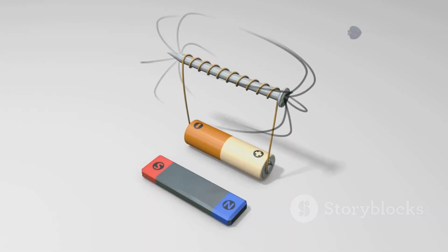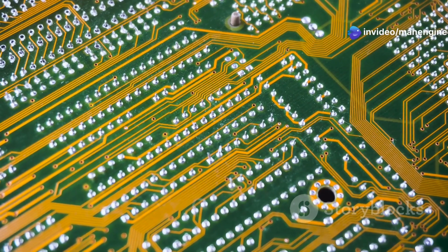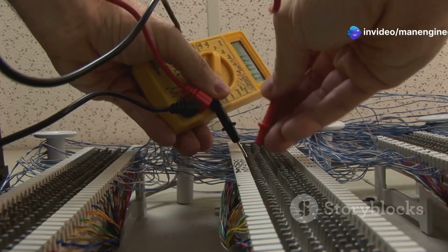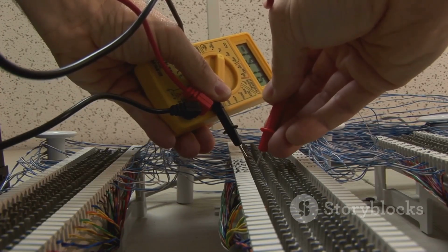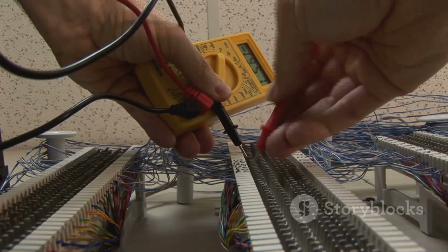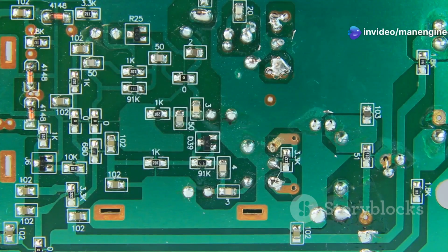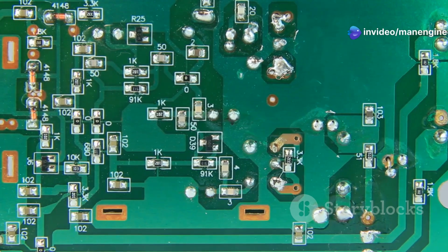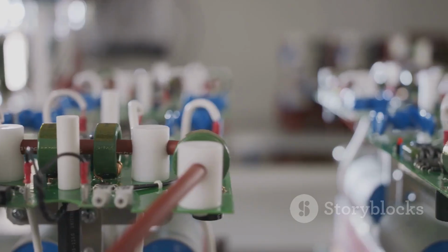When we have resistors in series, something interesting happens with the voltage. This is called voltage division. In a series circuit, the total voltage supplied by the source is divided or distributed among all the resistors in that series chain. Each resistor gets a certain share of the total voltage, and this share is directly proportional to its resistance value. A resistor with a larger resistance value will have a larger voltage drop across it.